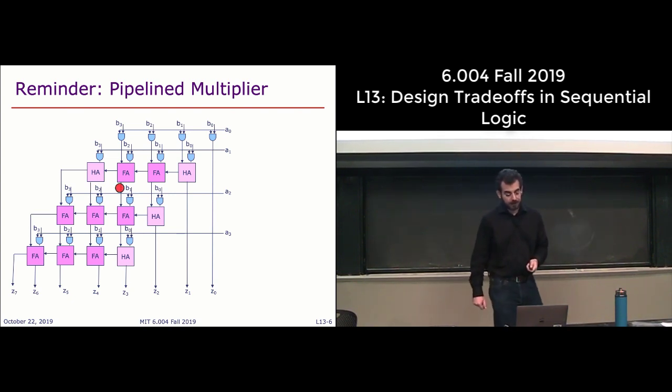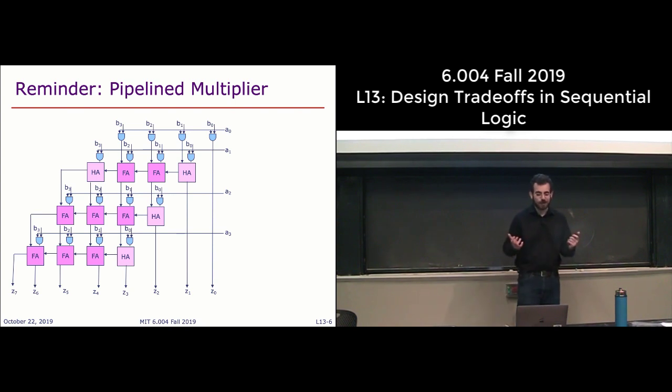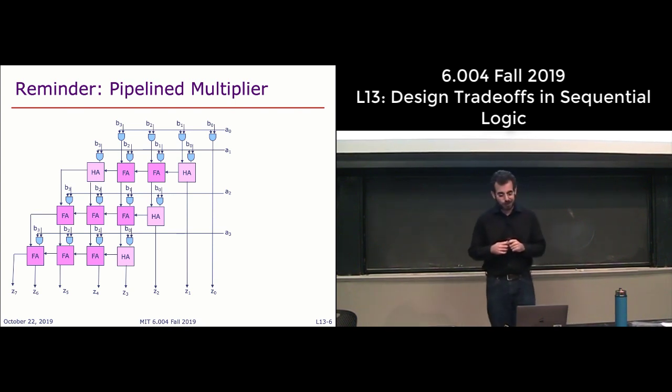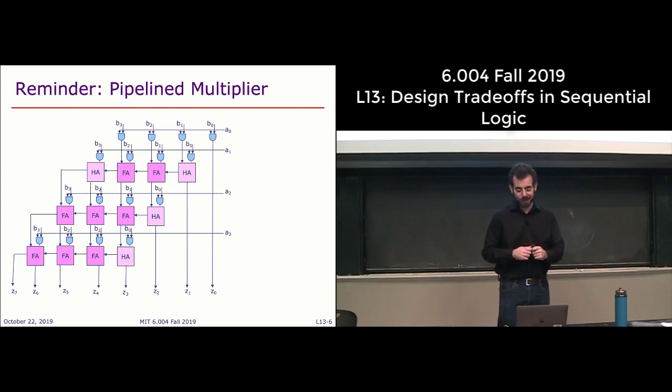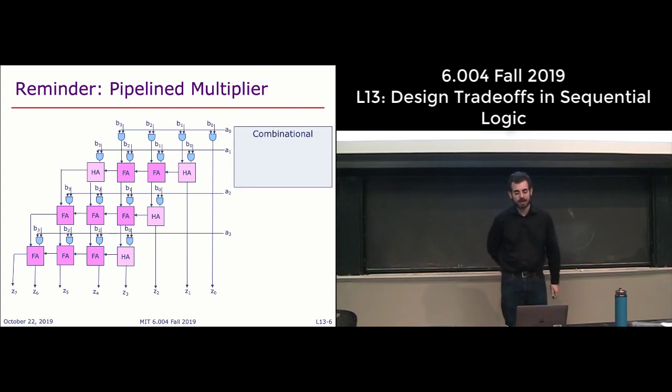And so then what we do is we first compute the partial products, basically multiplying the input B by each particular bit of A. And because in binary multiplication is just an AND gate, these partial products are very easy. We've all learned fairly large multiplication tables in middle school. Well, my favorite thing about binary is the multiplication table. It's as simple as it gets, right? So you don't need to do anything complicated to compute these partial products. This is just an AND gate. It's either 0 or the original input.